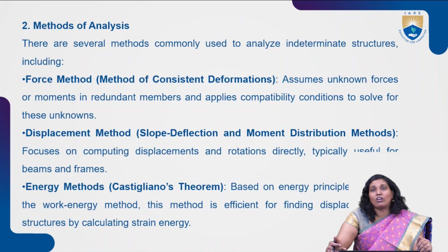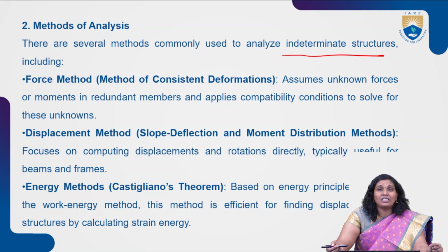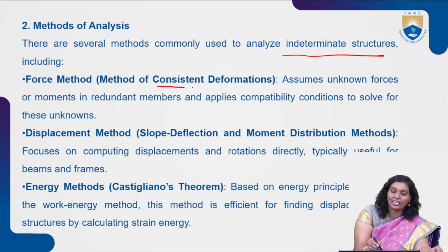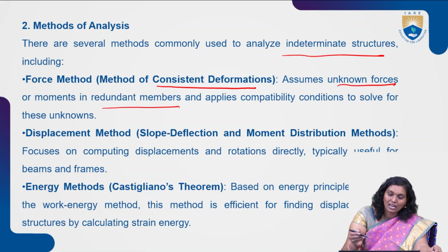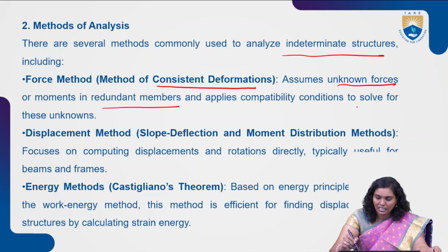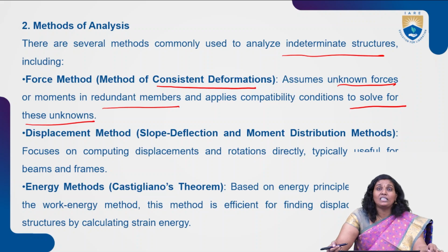And this method of analysis, there are several methods commonly used to analyze these indeterminate structures: force method, displacement method, and energy methods. In the force method, the method of consistent deformations, force method is nothing but the method of consistent deformations. Here in this particular method, we assume unknown forces or moments in redundant members and apply compatibility conditions to solve for these unknowns.